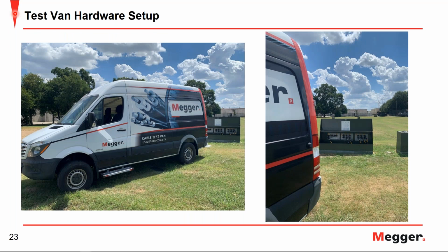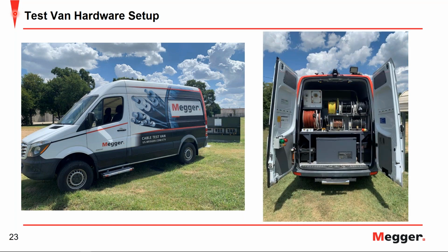Once we've inspected and ensured that we have a good ground, we can go ahead and back up our test system as close to our test object as possible. You may not always be able to get this close, but you want to try to keep your connections as short as possible, so backing up as close as possible is always ideal. Here we have the test van solution that's your all-in-one. As you can see back here, you can do anything from cable fault location to diagnostics. But obviously we're interested in doing partial discharge testing.